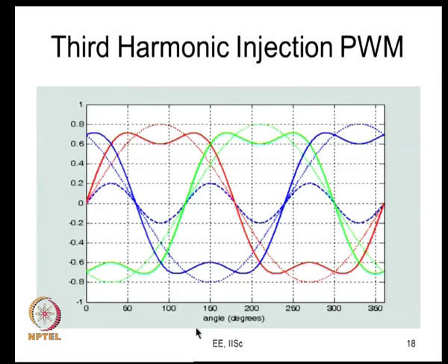In all these, this is some continuous modulation. What happens is there is always a phase that switches once. So, sometimes the phase may be carrying a high current, let us say the power factor is near unity. So, the fundamental voltage is high, the duty ratio is high, and the phase current is also high, and the phase is going to switch now. Here the phase current is going to be low, but still the phase is switching once. Here again the phase current will be high, though in a different direction, and the phase continues to switch.